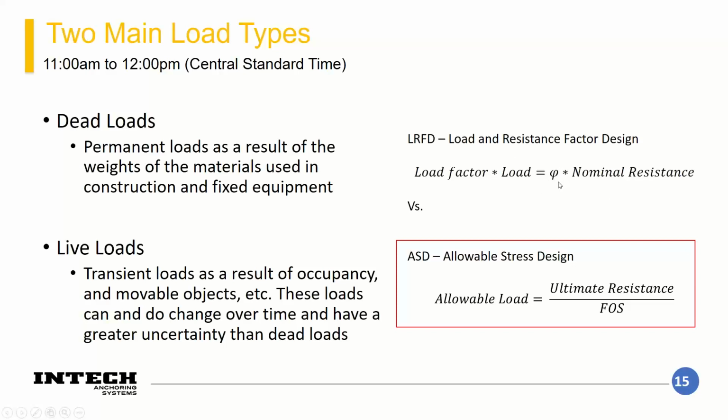So when we have a soil resistance right here, the uncertainty in that is much greater than the uncertainty you'd have for steel, or even concrete and wood design as well. So that's why we like to stay in the ASD design space when you're looking at foundation loads.